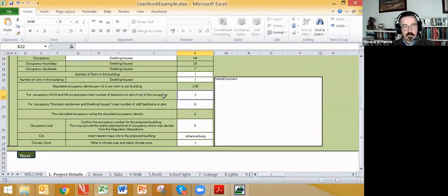The software automatically extends that 3 bedrooms by the statutory 2 persons per bedroom in table 2 of paragraph A21 of part A of the National Building Regulations, or rather SANS 10 400 part A. So we've got a calculated 6 persons in occupation of this building.